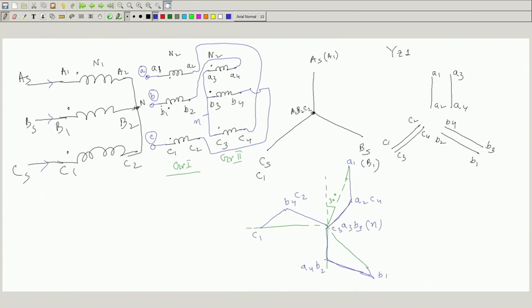Now, so far as the third harmonic voltage is concerned, you see they are cophasal. If this is plus, this is minus E third, fundamental I am not showing, and then this is also third harmonic E third. In all the coils third harmonic voltage will be induced, and so plus to minus and then minus to plus, and you reach the neutral.